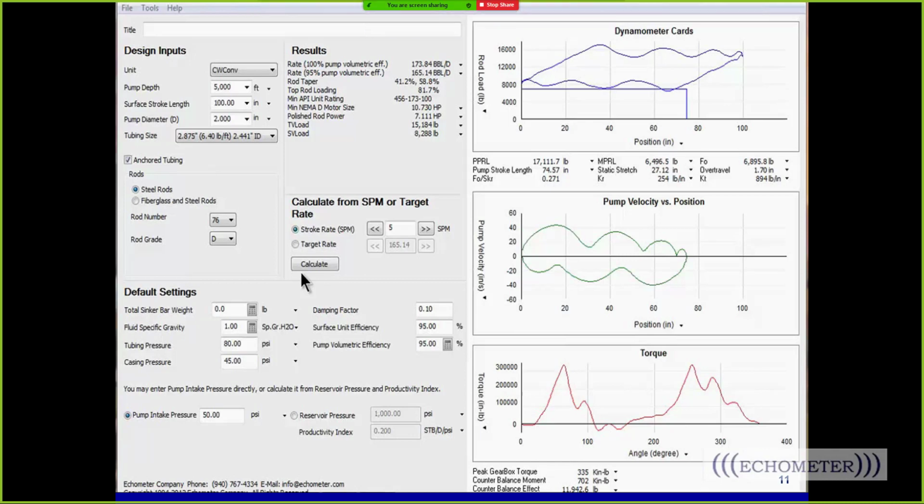Now, if you've rotated clockwise forever, and your gears are worn out in that direction, then that may not be a good direction of rotation. So, depending on gearbox wear and damage, there may be a preferred rotation direction for your unit. But normally, if it's in good condition, there's no preferred direction; the preferred method is the least torque on the gearbox.